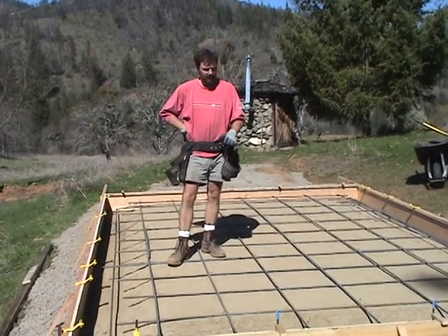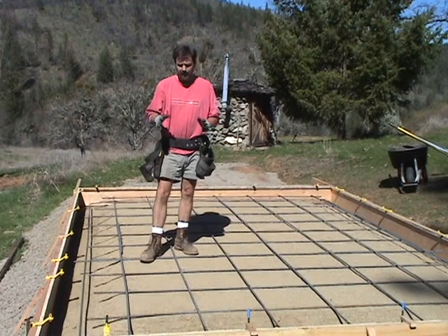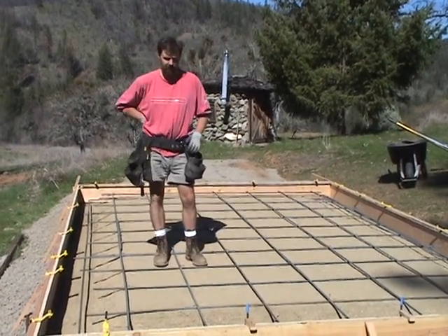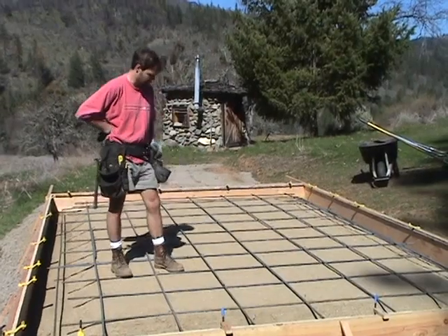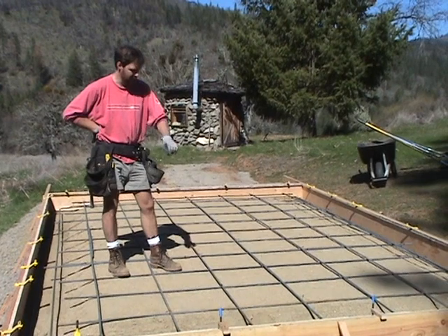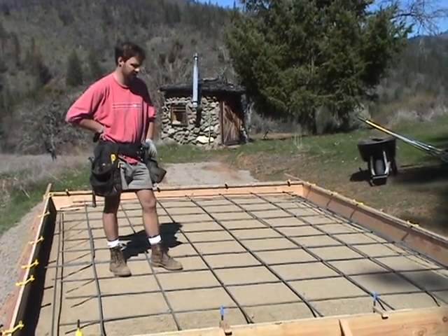So I've gone ahead and made a grid of rebar here on top of the slab, and basically we've got an 18-inch center, so 18 inches in each direction is the measurement for this grid. I use the same method of attachment using those twisters to attach about every other space. I don't attach every one, it's a solid grid in and of itself, just with every other space tied together.